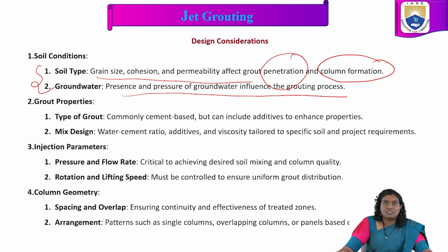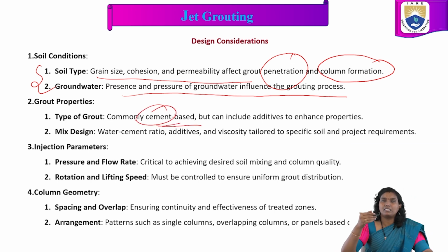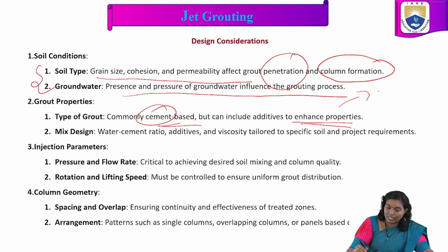Grout properties: type of grout, mix design. Which type of grout? Commonly cement based, but it can include additives to enhance the properties. Generally we choose cement only, but it depends upon the soil conditions at the location. If it requires any additions, we use those additives to enhance the properties or to get the desired properties.